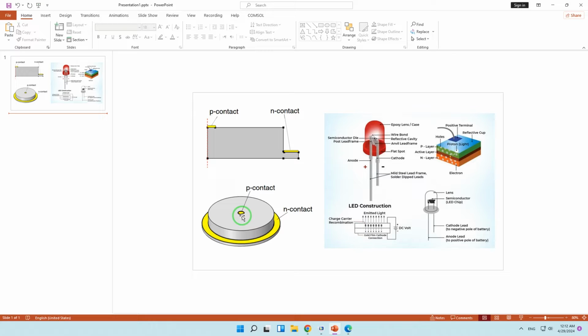This model uses two studies. The first is semiconductor initialization, and that is used to automatically refine the mesh around the gradient of dopant concentration. This is useful because the refined mesh is denser around the p-n junction, which is where a smaller resolution is required. The second study sweeps the voltage bias across the device from 0 volt to 1.5 volt. The current-voltage curve is plotted to show that the device is indeed a diode, and the emission rate throughout the device is calculated.